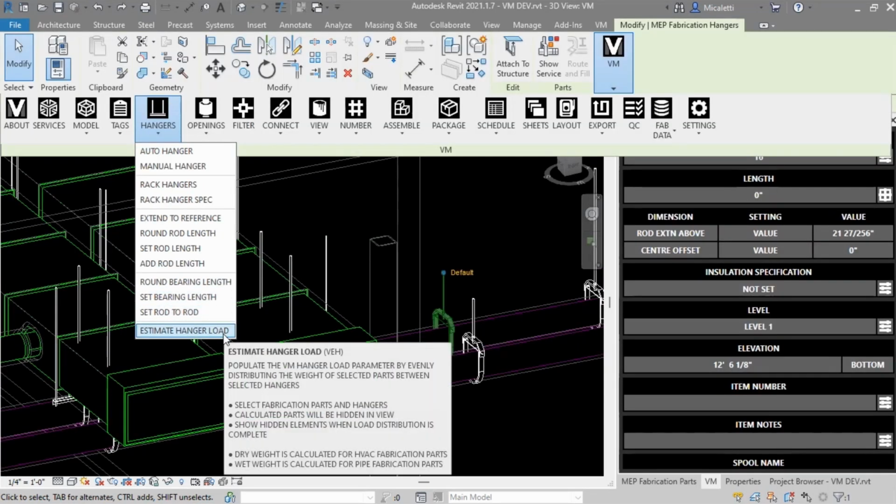Yeah, there's that. You can also estimate hanger loads. I don't know if you guys do a lot of that, but you can do that. In CAD, we have to do it every now and then, right? Especially when it comes to heavy grease duct, right? Where it's 16 gauge and has all the fire wrap. So we have scripts that grab all the associated ductwork and divide it up, and tag it, and then we have the block tools that snap blocks onto the hangers. It's only in CAD though, so I'm curious how your Revit one works.